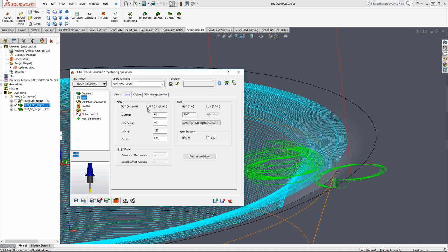And as far as the inch per tooth, what I discovered through some research and talking to some different tooling vendors, especially with ball nose and the cusp height or the step over, their rule of thumb suggestion was if you had, let's say, a .020 step over with a half-inch ball, it kind of calculated out to maybe a .0001 cusp height.